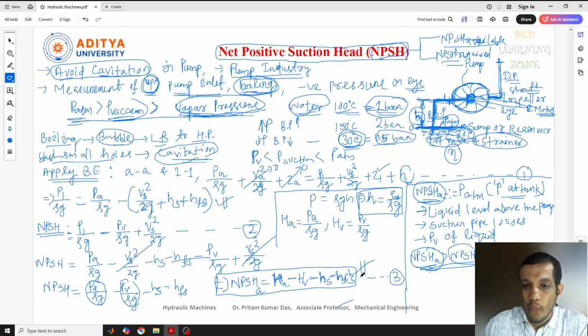So if you want to operate our centrifugal pump without any cavitation, then the available NPSH should always be greater than the required. This is my final statement.